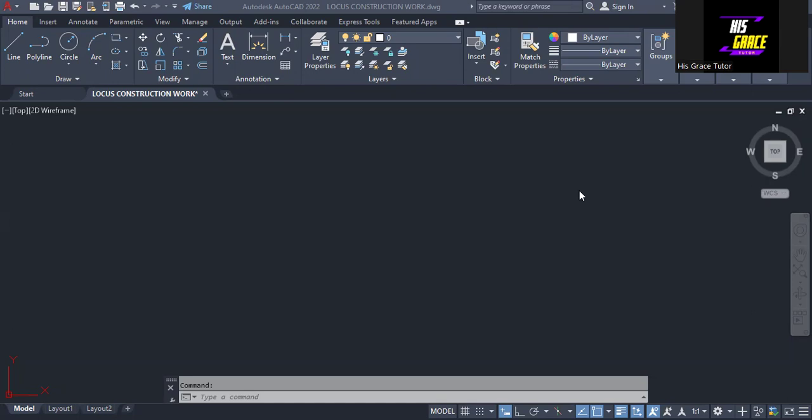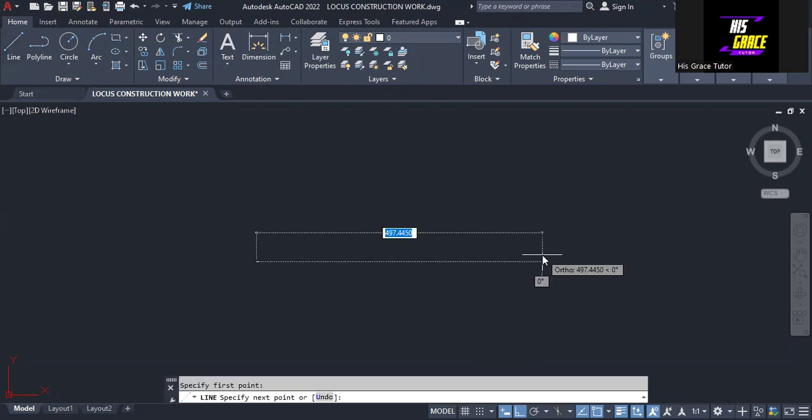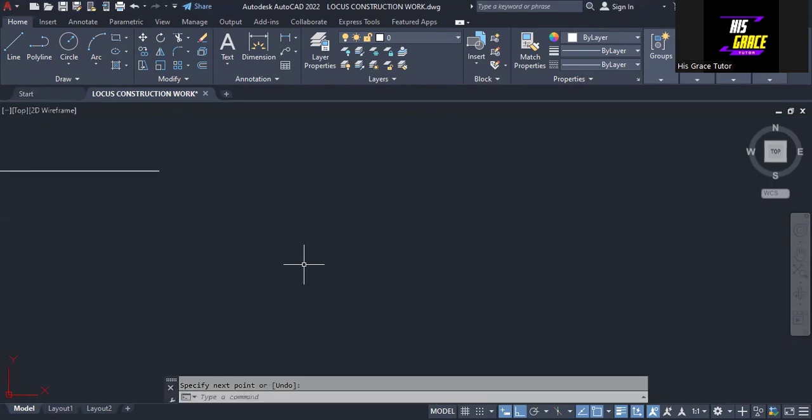So what we have to do first is to draw the major and the minor axis, and it goes as follows. We need to make sure we put on the auto mode, or activate it, or enable it. Then we go to line, and draw a horizontal line which is going to stand for the major axis, 120. Enter. All right, so we have it like this.